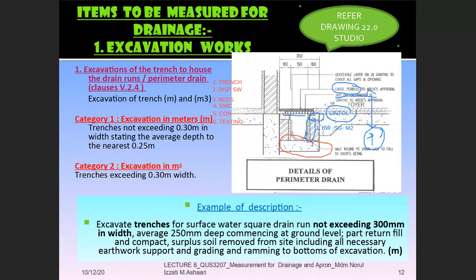Loose pebble, anyone know? The word pebble is the small stone, very small, nice stone that is arranged on the top to cover the jointing. Okay, so loose pebble is measured as floor finishes because this is a type of floor finishes. Measured in meter square under section S.